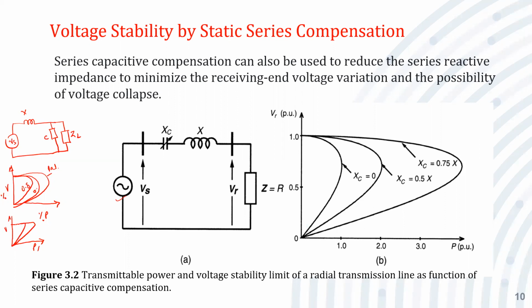Such type of curve for the different power factor. So it is found that because of the shunt compensation which is connected near to the load, the requirement of the reactive power is going to be fulfilled by the compensator. The compensator connected near to the load is going to supply the leading kVAR or MVAR required by the load,